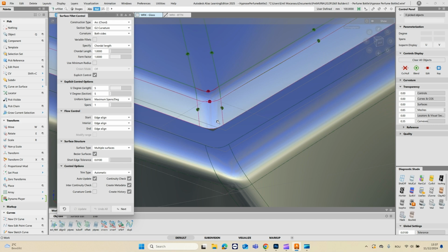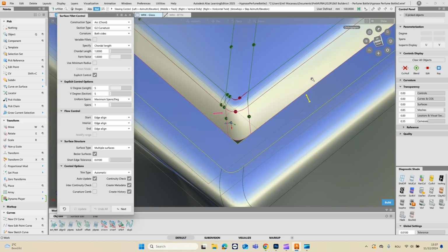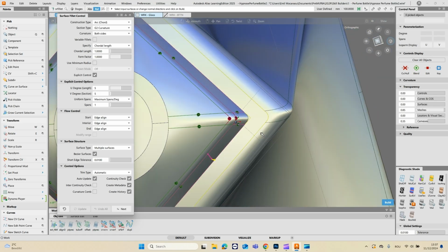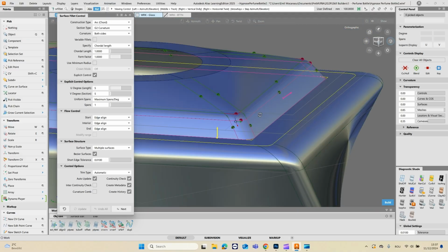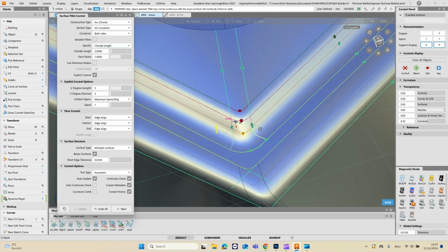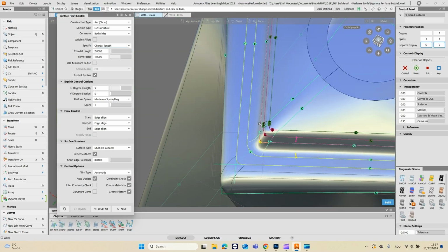So I'll go ahead and build a radius between these walls and that base surface there. I want this to be degree 2, a size 2 mil, and it does it nicely, so thank you for that.